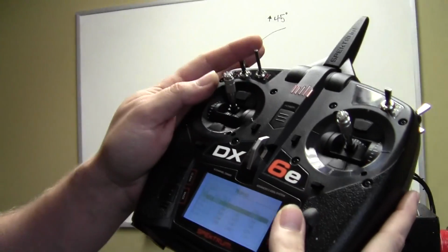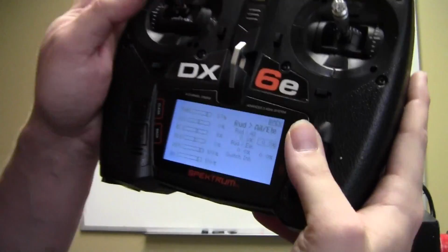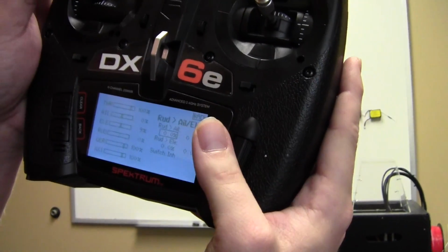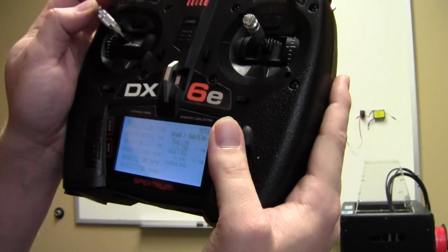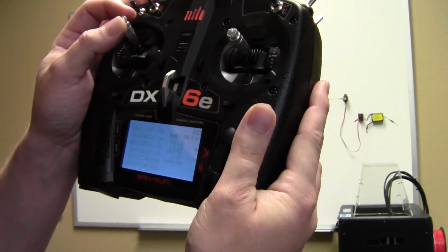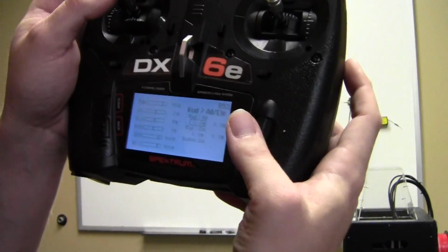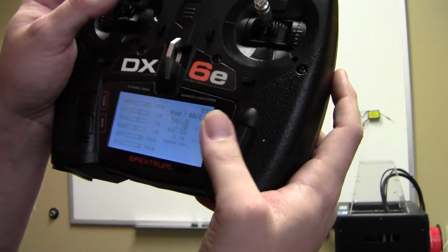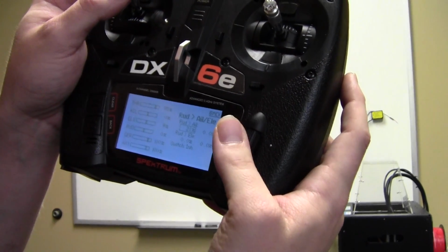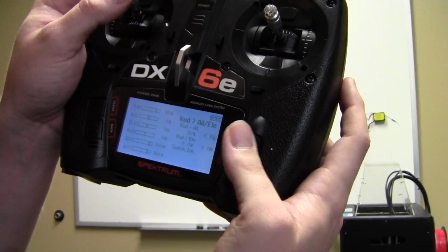So you can use that to incorporate. Let's kind of pretend we're doing that. So when we give it rudder, when we're flying it, we see, okay, when we give it full rudder, our left wing wants to go down. So we put in a rate, say 20%, to make it visually appealing.